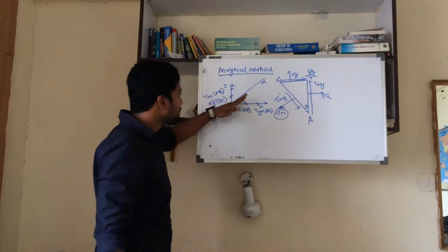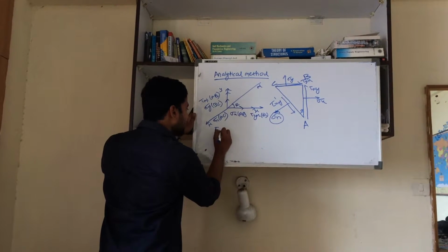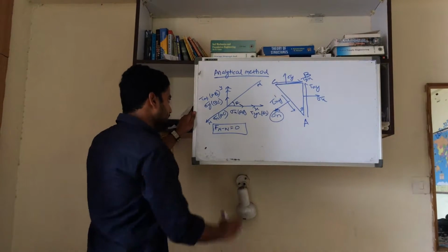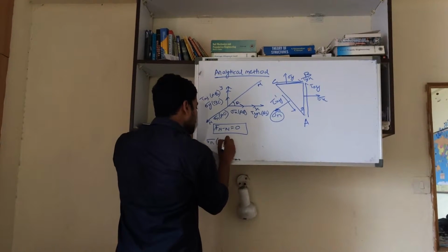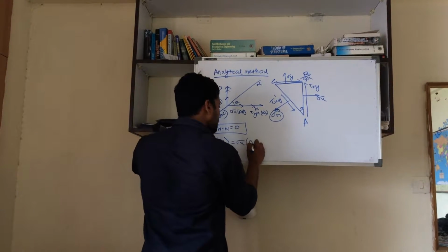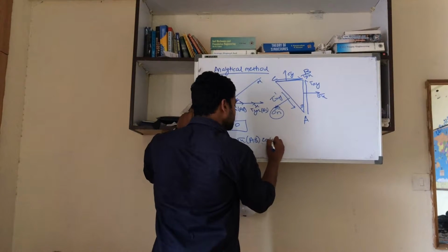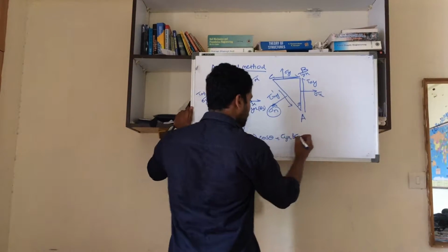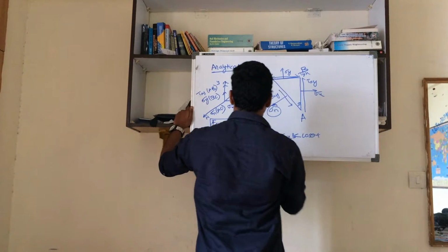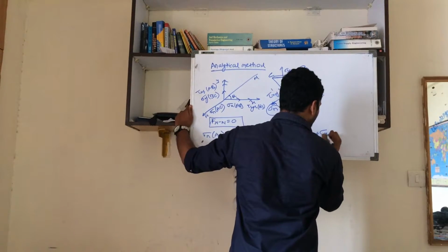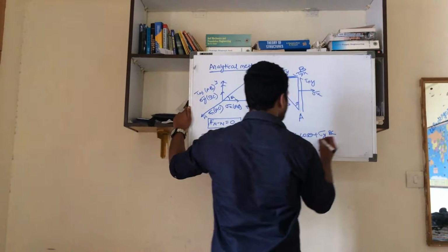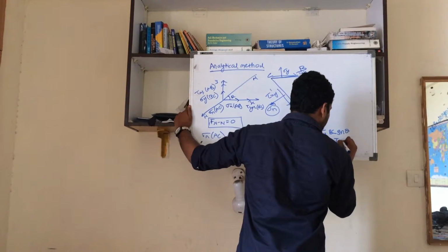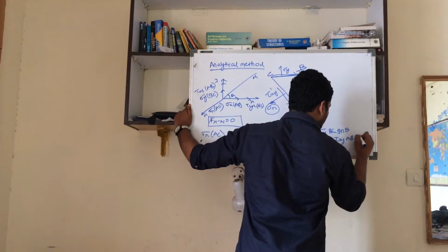If you equate the forces in the n direction, that is, sum of F n equal to 0, then you will get sigma n multiplied with AC equal to sigma x AB cos theta plus tau yx BC cos theta plus sigma y BC sin theta plus tau xy AB sin theta.